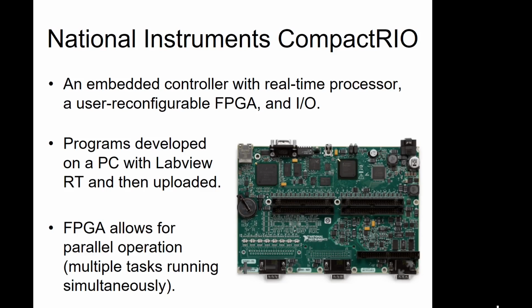LabVIEW has an option called LabVIEW Real Time, LabVIEW RT, and this allows you to program this board using the LabVIEW language. So it is an option. We have got some at the university. As I said, it's very good if you need real-time speed in your system. Some of these boards were used when we were first developing driverless cars. Some of the initial projects were using things like LabVIEW FPGA boards to perform these tasks. So they are potentially very powerful if you need that.